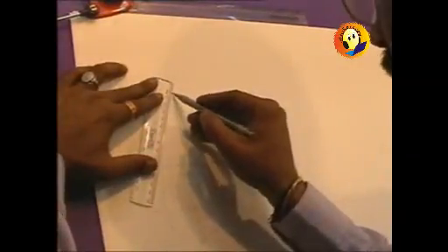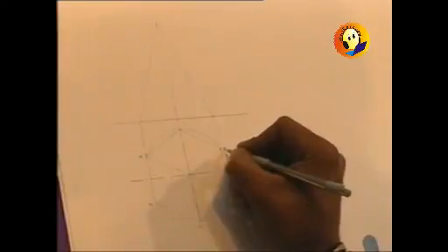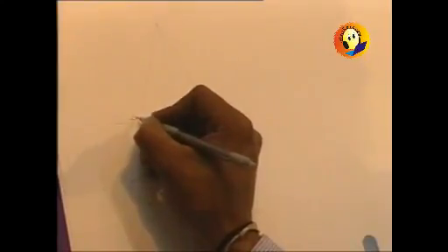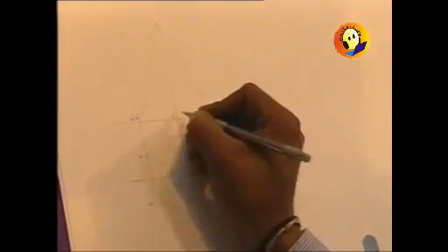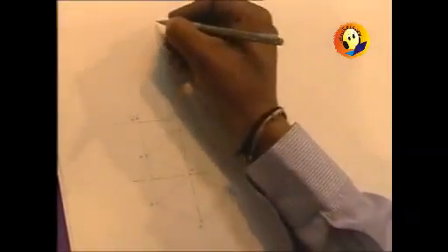Up till now we have not named it. So this is how we start with the solution. We have drawn the hexagon in the top view and the triangle which will represent the front view of that particular pyramid. Now we are required to first of all name it. So I am going to name it as A, B, C, D, E and F, whereas the vertex is V. The points of the elevation will be A', B', this is C' and F', and this is going to be D' and E', and this is vertex V'.